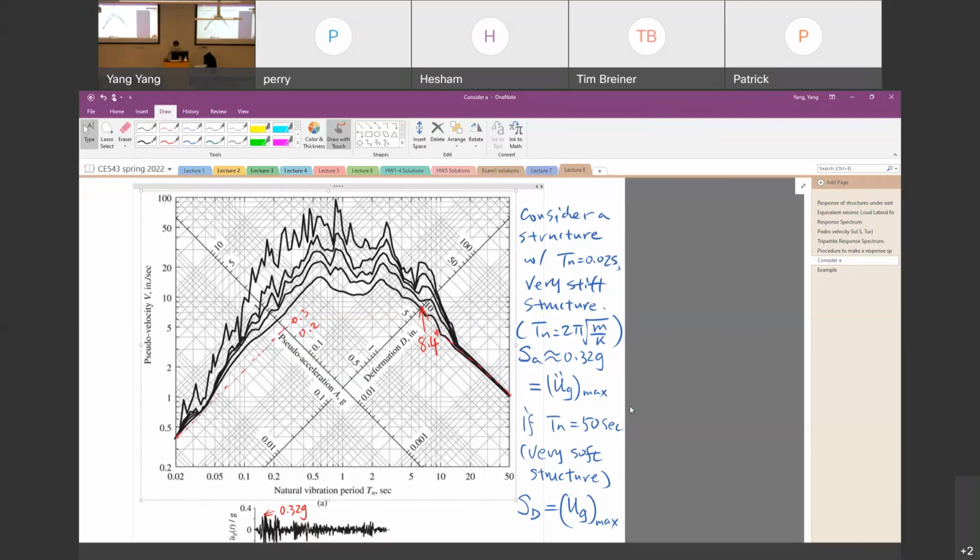That's why seismic design is so different from the conventional design. In conventional design, you only need to consider the strength. If the design strength is larger than the required strength, you see that the structure should be okay. But in seismic design, that's a different story. Unfortunately for this class, we will not talk in more detail about displacement design. Displacement design will involve nonlinear analysis, especially regarding the ductility analysis.